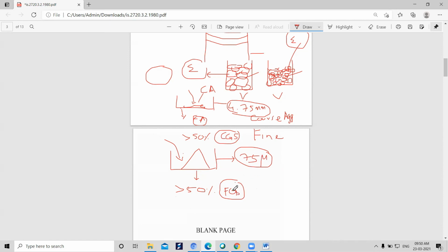If fine grained soil is present, to find out the specific gravity, which bottle do we have to take? Come on, it is the density bottle. Right? If it is medium to coarse grained soil, then which bottle do we have to take? Quickly say. Pycnometer. Right. Clear? Did you understand?